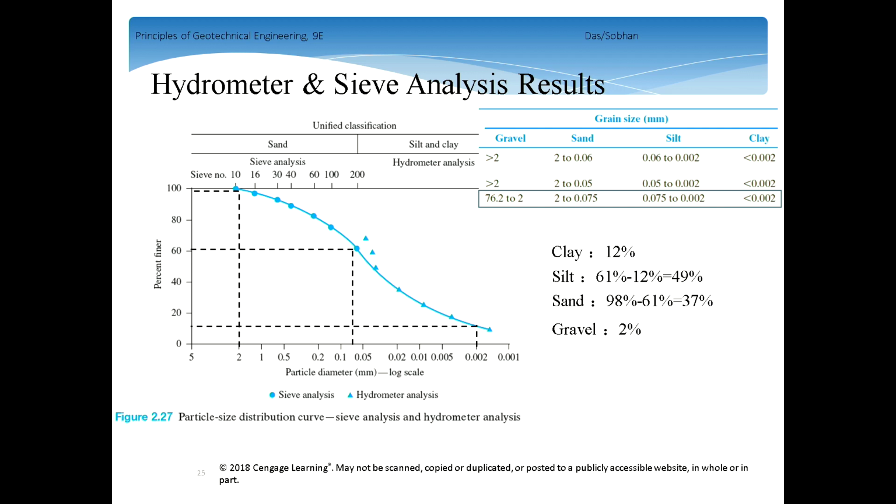If you want to get the total particle size distribution curve from large particles to very fine particles, you need to conduct both tests. But if you just want a rough particle size distribution curve, sieve analysis is actually enough. In most cases, we just need to do the sieve analysis to get to the important part, that's this part.